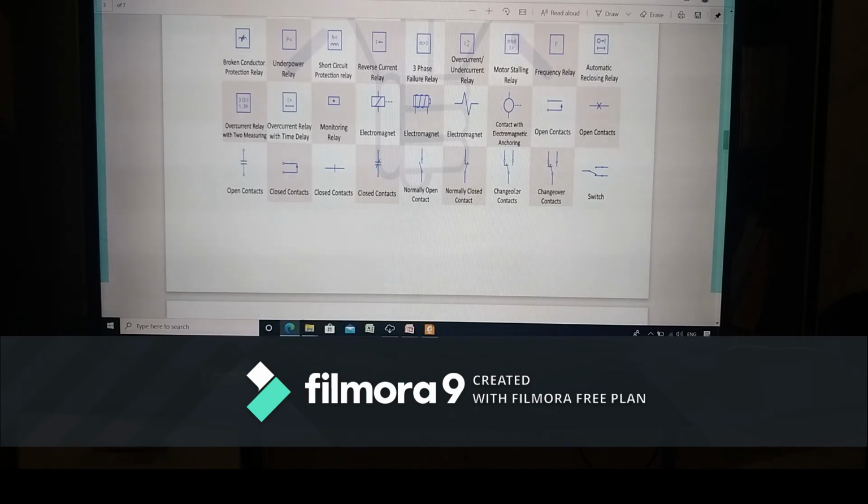And this is changeover contact. Changeover contact is nothing but 1 NO 1 NC. It changes according to the condition changes. That means it has two contacts, one is NC and one NO. The common contact changes its position when it gets supply, from NC to NO. So that's why it's a changeover contact.